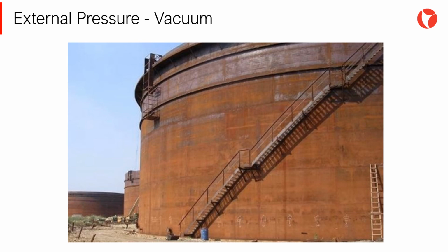The design of stiffening rings on the wall of the tank for both loads, wind pressure and due to external pressure, must be carried out jointly. Although it is true that the requirements are different for these two conditions, the design must be carried out with a global vision of the tank.